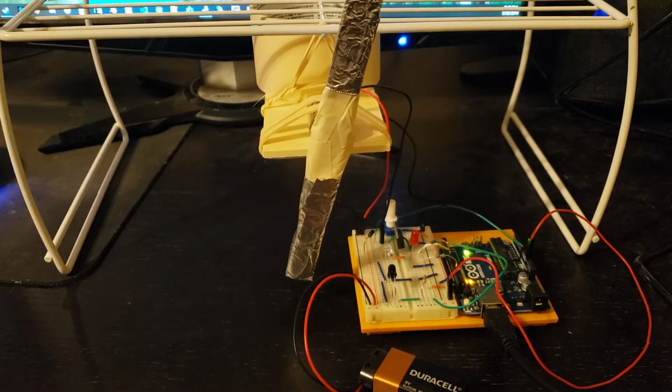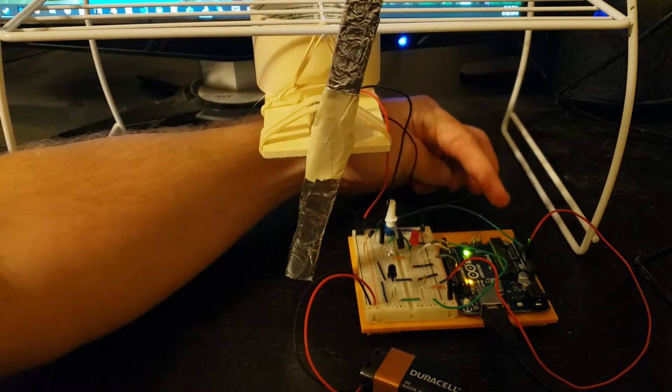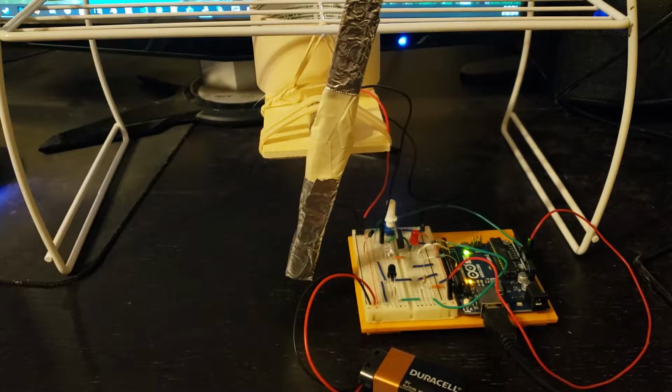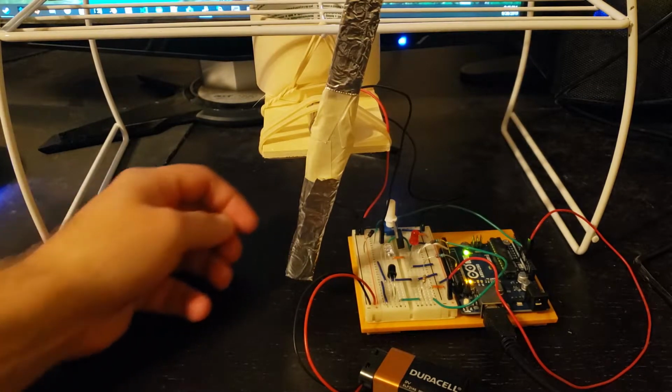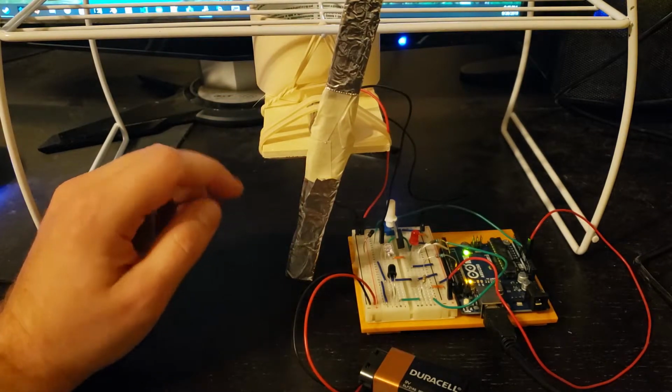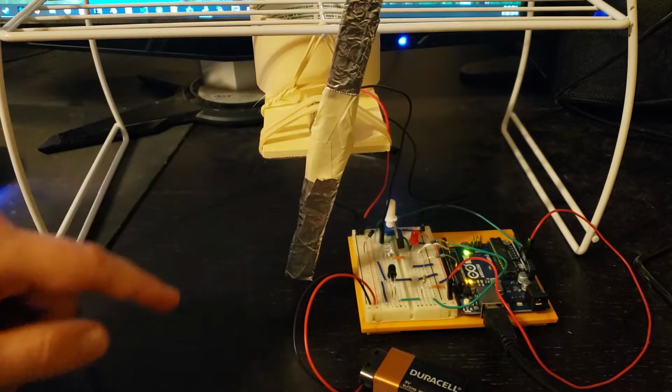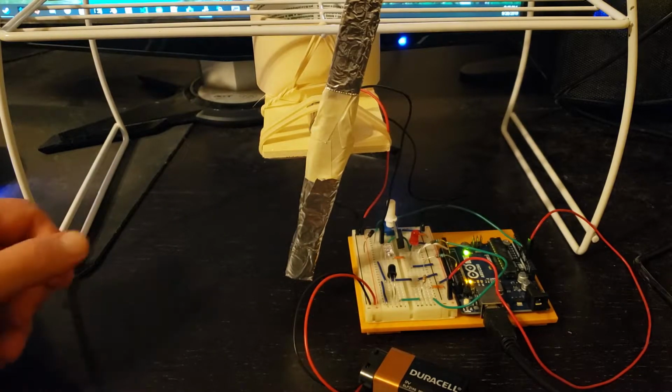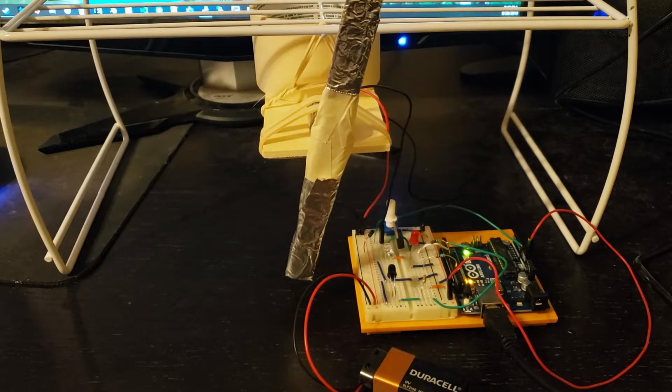The ADC value is connected to an analog pin over here, so that's a 10-bit value that comes in, and since the pulse width modulation is an 8-bit value, I had to map the 10-bit value to an 8-bit value, and that value is read by the main loop at a rate of 10 Hertz. As I turn the potentiometer, you'll see in the demonstration that the DC motor will speed up, and if I turn it back down, the DC motor will slow down.